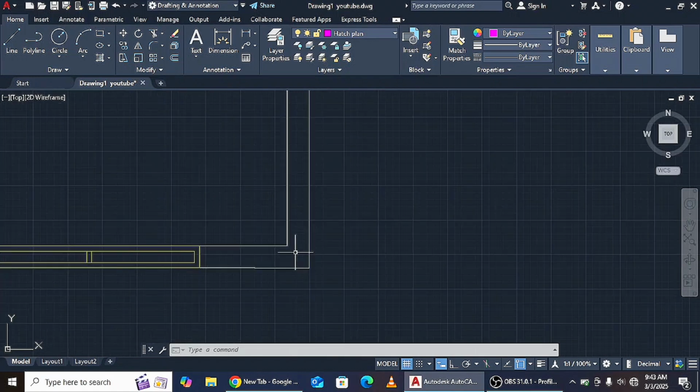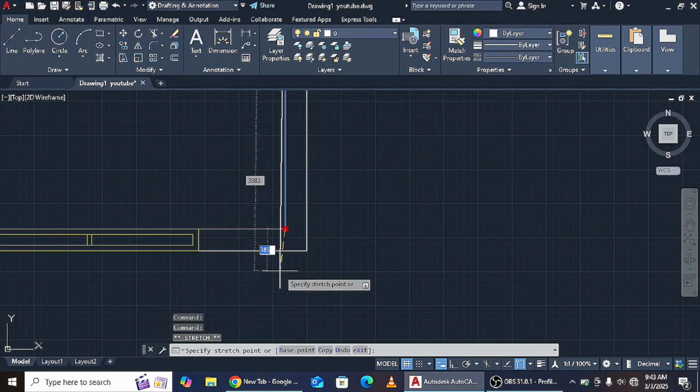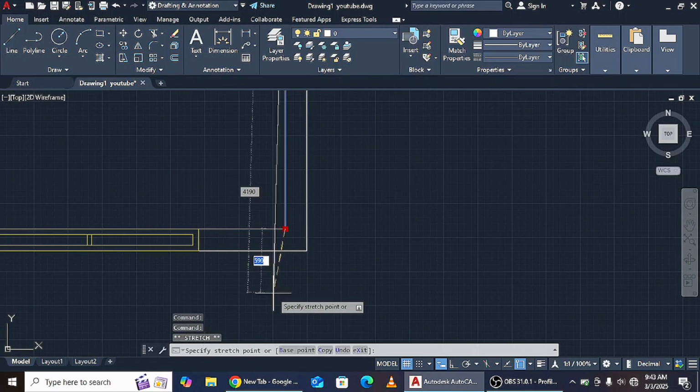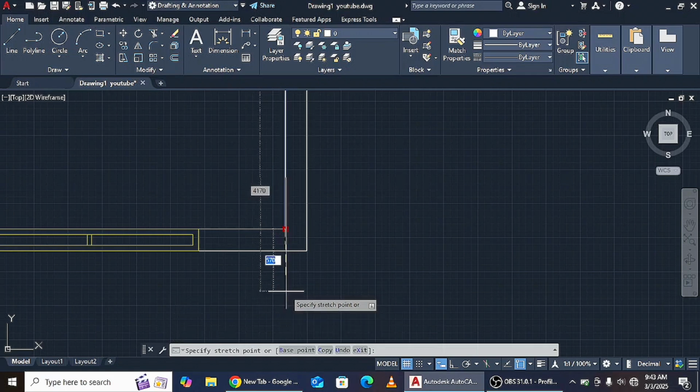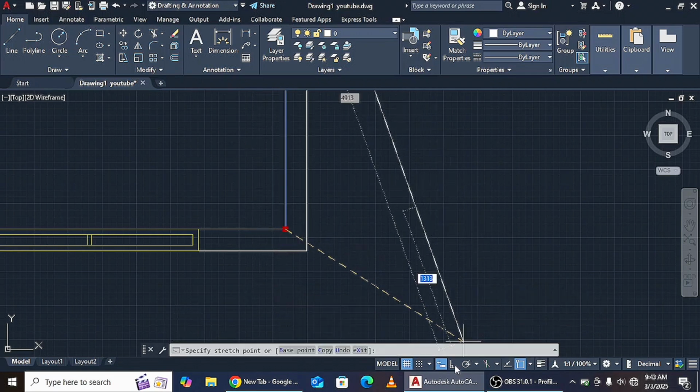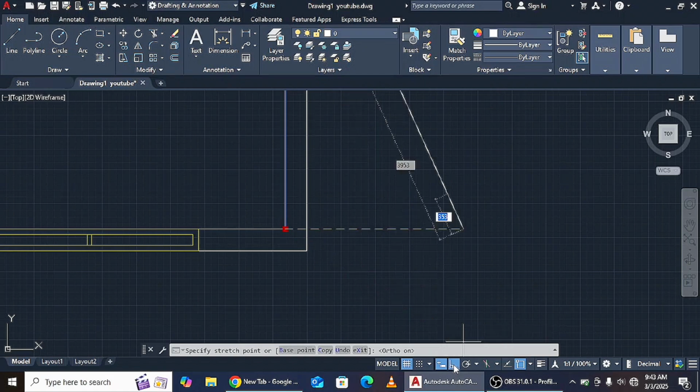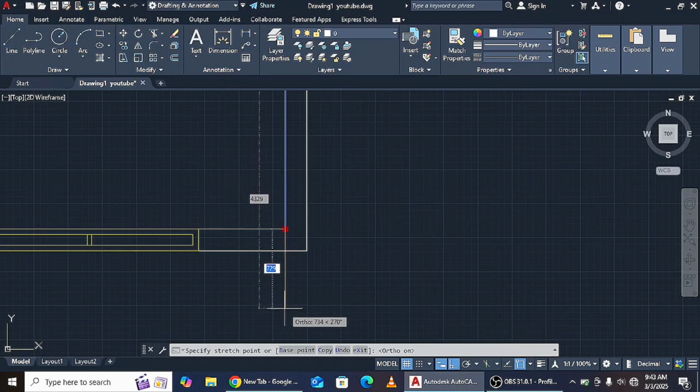They are joined. This other line was also having issues, so I'm going to drag this line. You realize that I want to drag it through 90 degrees, but I can't because my auto mode is switched off. So I'm going to turn it on. We click on it so that I can draw a perfect straight line.